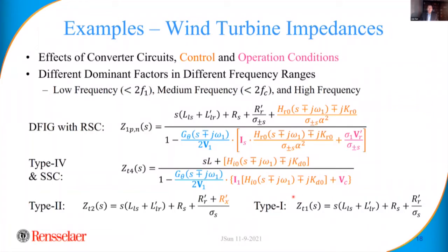Right? So you can make a lot out of this simple model. DFIG, or the type 3 turbine, has a similar form of model. You read it. So there's some added complexity here, but that's really because of the more complex impedance of the induction machine. The induction machine has inductance, but also resistance, and the rotor winding resistance has to be converted through the air gap, so that introduces this slip function. But the form of the model resembles that of the type 4 turbine.